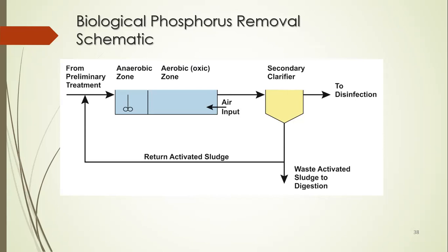So we will not go into the wastewater microbiology, but depending on the terminal electron acceptor of the microorganisms, the microorganism diversity will change. So when you have plenty of oxygen, the microorganisms which can survive under the oxygen-rich environment will dominate. But when there is no oxygen, the terminal electron acceptor would be nitrates, components like nitrates and so on.